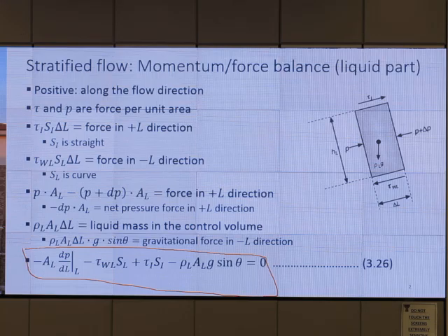June, do you think Shoham used it for turbulence or not? Obadiah Shoham. Did he? Who is Obadiah Shoham? Okay, the other group. Did he ever use it for turbulent flow, for that equation? Can you take a look on page 65? Is there anything about a Laplace type equation and 0.046 times Reynolds number to the power of minus 0.2? This is a smooth pipe. Yeah, that's smooth pipe, but it's turbulent flow. Yes. So Taitel and Dukler did that, right?